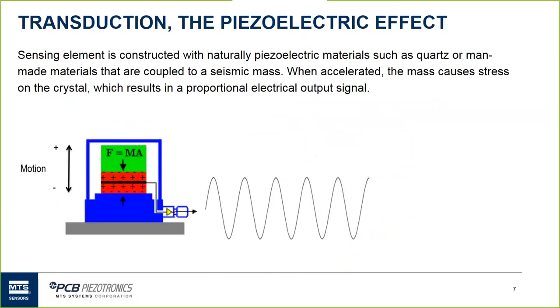So in the case of an accelerometer that's piezoelectric in nature, we have something referred to as the piezoelectric effect. In this case, the bottom gray bar represents where the sensor is mounted, and then motion's imparted typically through the base of the accelerometer, and that motion results in force being applied to sensing elements, and that results in an output referred to as a picocoulomb.